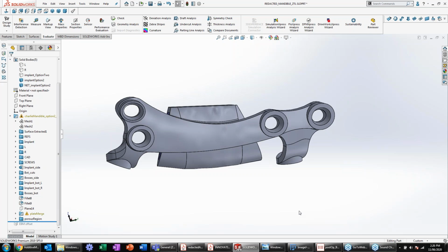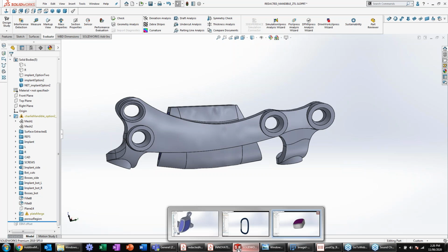Yeah. So one of the other benefits to additive manufacturing is mass customization. So we have some customers that send us some files that are very similar, but they're all just a bit different. But they're not producing enough of these to sort of tool up, because they're only doing one or two off, and then it's a new geometry. And they're all pretty much the same part, but a bit different. So when you got something like that, that's when parametric design makes a lot of sense.